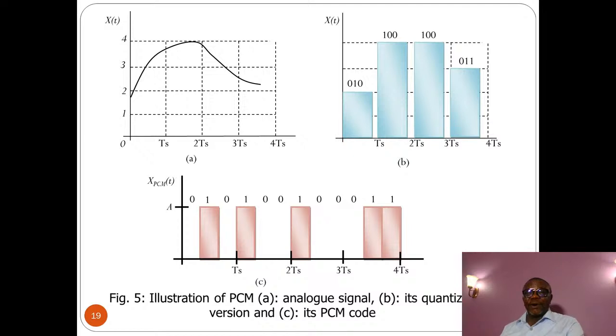Now, the second blue pulse, which is 100, it transmits a 1, the second pulse, purple in color, that starts at TS. It will transmit a 1 and a 00. 0 could be blank space, 0 could be a negative pulse going down. In this case, we are using blank space.